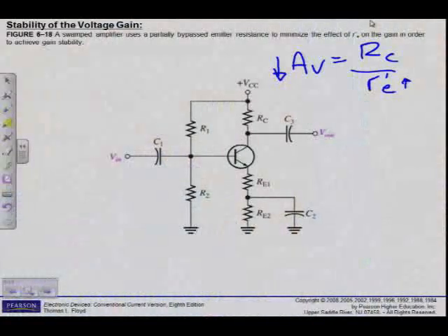Alright, so with no bypass capacitor, the gain is decreased because RE is now in circuit. So, how do I get rid of this problem? R'e changes with temperature and IE. Although I get maximum gain, it's of no use to me. But if I include RE, what have we seen happen to the voltage gain? Becomes 1.7 something. Down from 152 in this example. Okay? That's also not a very good situation. Doesn't amplify much. So what we do is we use a method called swamping.